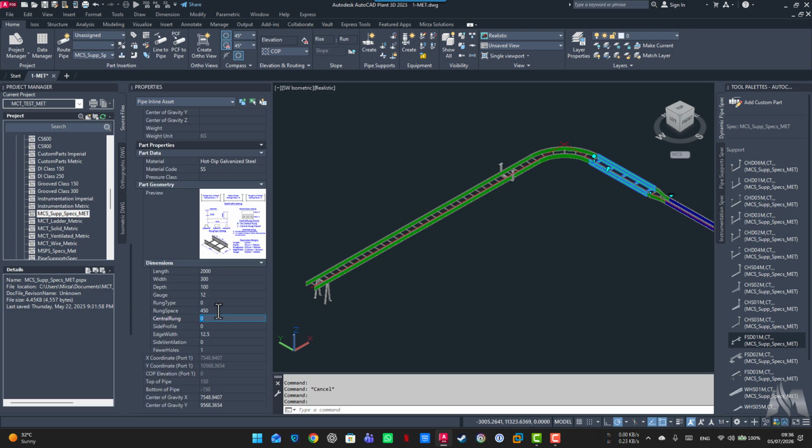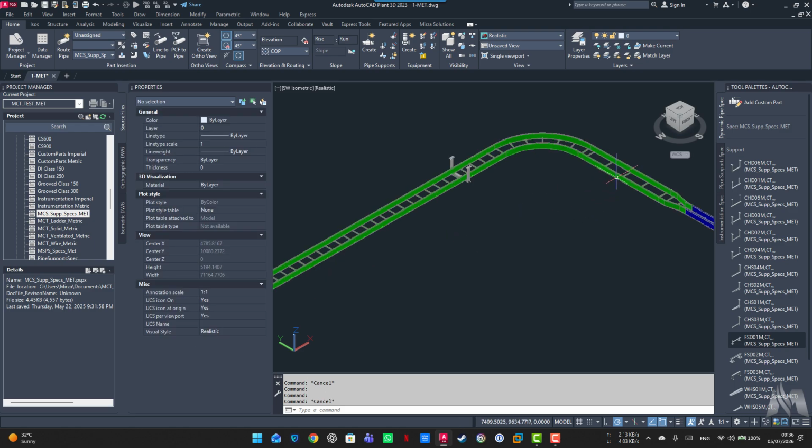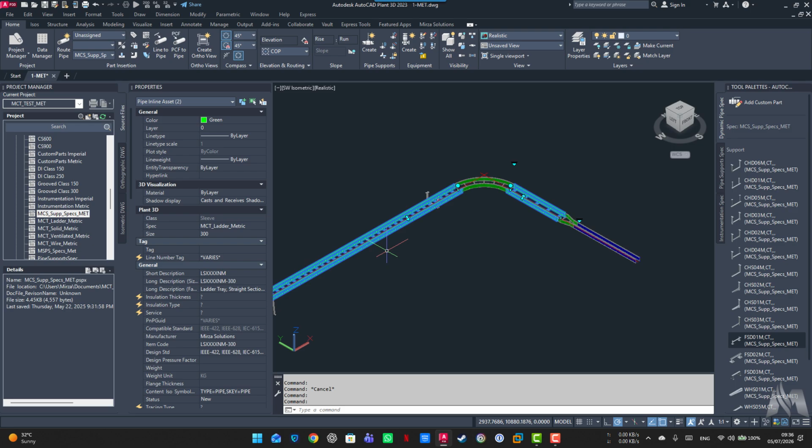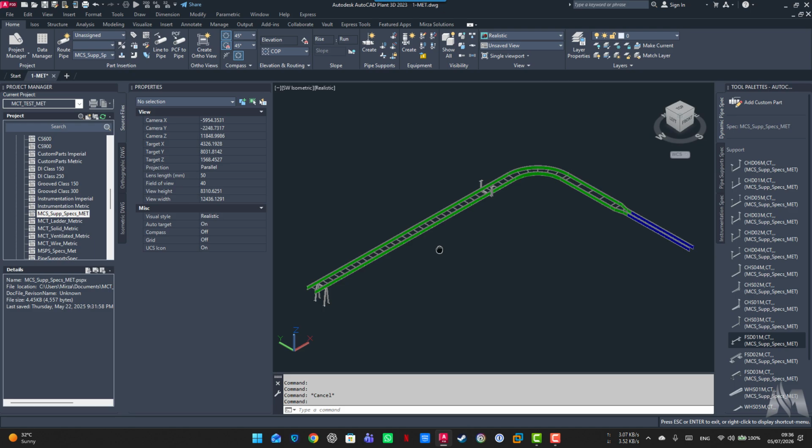Now technically this cable tray and this cable tray are two distinct cable tray sections. And in the BOQ system and the isometric for the cable tray, these should be identified as two different elements. But in the default environment of AutoCAD, they are not. Let me show you.